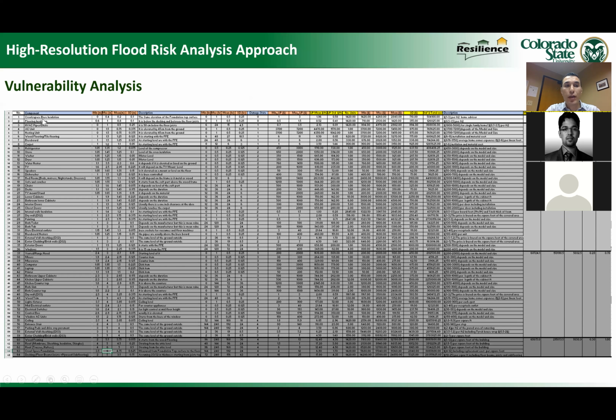So we have the crawl space isolation and the flooring insulation. In damage state 0, we have the HVAC and the AC unit, heating unit. In damage state 1, we have the appliances, refrigerator, stove, dryer, washer, lower cabinets, TVs. Damage state 2 and damage state 3 include counter items, upper cabinets, electrical receptacles. And damage state 4 includes the wood framing, the roof sheathing, the roof framing, foundation. So we grouped these components based on how they are associated with each damage state.